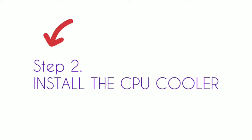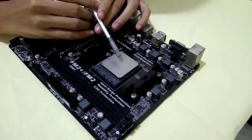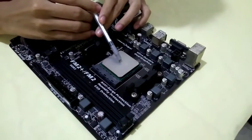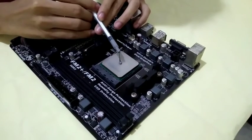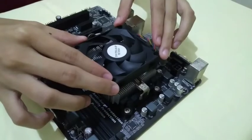Step 2. Install the CPU cooler. Apply thermal paste to the back of the processor. Seat CPU cooler and fix in position. Plug cabling connectors from the CPU cooler to the motherboard.